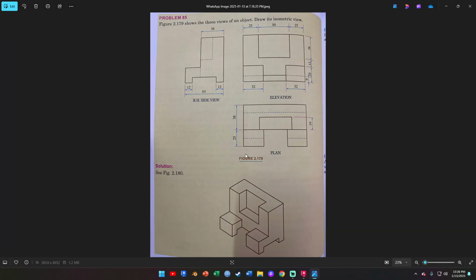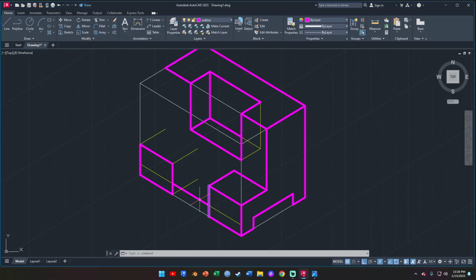So let's look back at the drawing here now. We basically have to do the same thing for the other leg here. Remember, you have this 12 mm coming in, and going up you have the 9 mm. So we can delete this one line here because it's supposed to go in 12 mm. So we're going to switch back to construction line, and seeing that this line is on the right axis, just make sure that your isoplane is on the right.